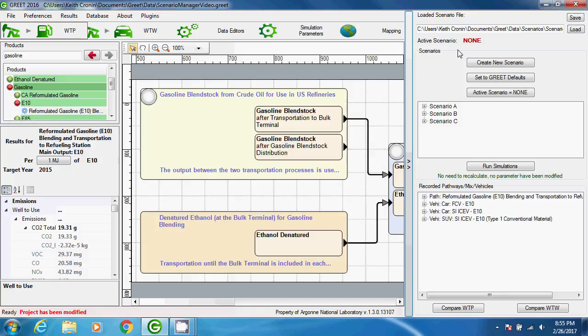Next below is the Scenarios frame, where you build your scenarios, and you'll see a few buttons here. The first is for creating scenarios, so clicking the button generates a new scenario that appears in the field directly below, and you can create as many new scenarios as you'd like using this button. The next two buttons help you direct which scenarios are modified when changes are made in the model, and I'll show how to use these in the example demonstrations.